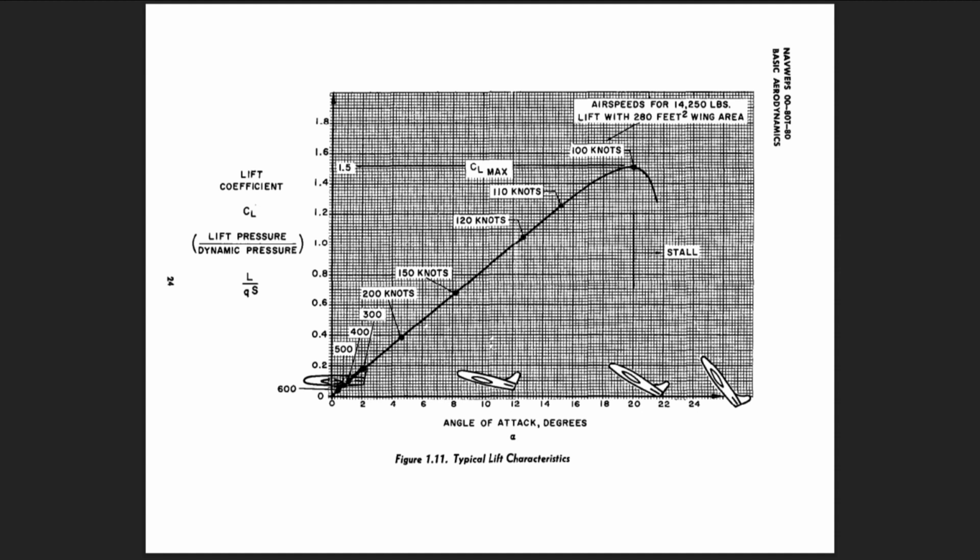One important fact to be appreciated is that the airplane shown in figure 1.11 stalls at the same angle of attack regardless of weight, dynamic pressure, bank angle, etc. Of course, the stall speed of the aircraft will be affected by weight, bank angle, and other factors since the product of dynamic pressure, wing area, and lift coefficient must produce the required lift. A rearrangement of the basic lift equation defines this relationship.